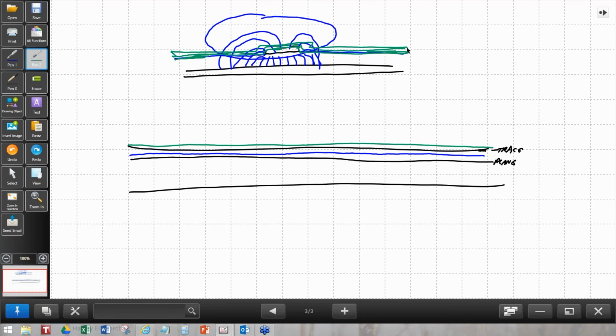It also will control how many of those field lines are up high versus actually being bent down low. So the more dielectric on top, the less amount of magnetic and electric field actually project up above the board. So you can't just say that the solder mask has no effect on characteristic impedance. It does on the outside of the board.